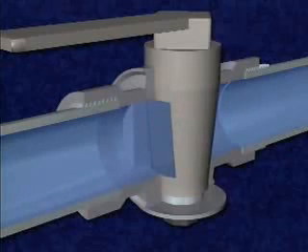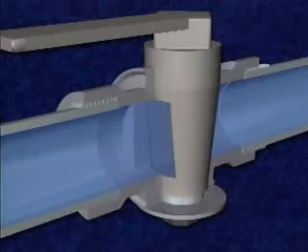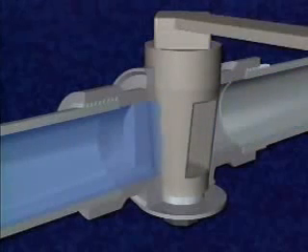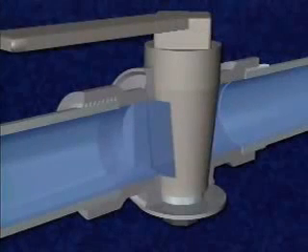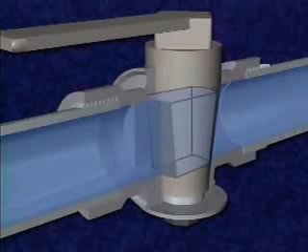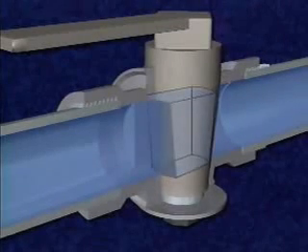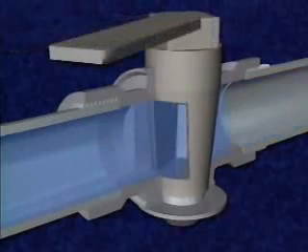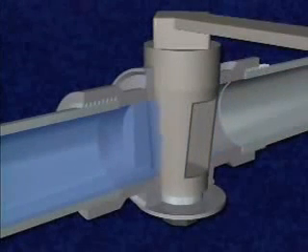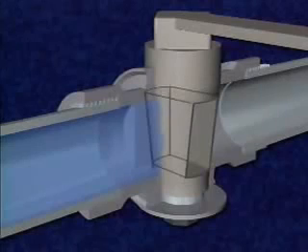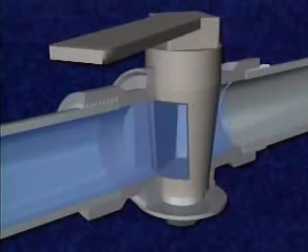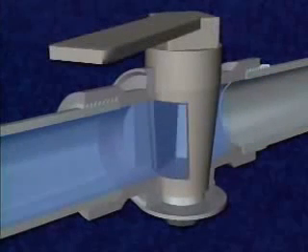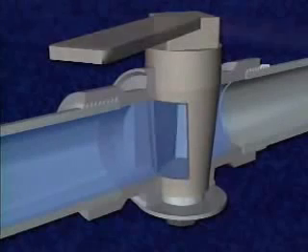Plug valves are generally used for on-off control in applications that require a tight shutoff, as in this gas line. When the handle is turned, the disc makes a 1/4 turn that quickly opens or closes the valve. When a plug valve is fully open, the ports in the disc, or plug, are lined up with the inlet and the outlet of the valve body so that fluid can flow through the valve. When the valve is fully closed, the plug is turned so that its ports are perpendicular to the valve body's inlet and outlet. For proper operation, the plug has to be able to turn in the seat, but the plug and the valve body must fit closely, so there's no leakage around the plug when the valve is closed.